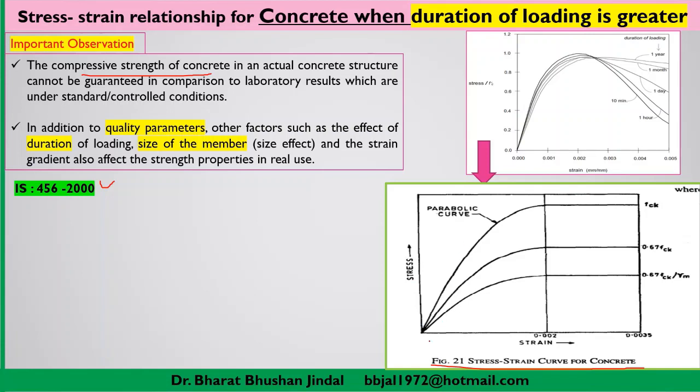Now you can see here what we have already told, that up to strain 0.002, the curve is a non-linear part, and at a strain level of 0.002, maximum stress is reached, and beyond that, as we considered in the earlier section, the stress strain graph will be linear, just like a flat curve. So you will observe here. Now we will be focusing on the first two curves. This curve we will discuss later on.